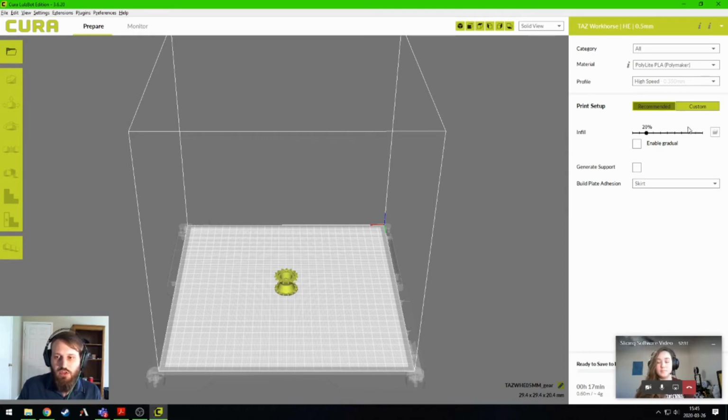So this isn't changing its shape right here. This is going to be how much infill we have in the object itself. With 20% infill, and this is usually a standard that I see, 10 to 20, depends on the object that you're printing, but in most cases I see it at 10 to 20, it's going to be 10% of that object's mass on the inside is these concentric lines. The higher you go, the more mass you add. So if I do this here, after slicing at 90%, I increase to 5 grams. And this will also adjust your time as well. 100%, 5 grams, 19 minutes.